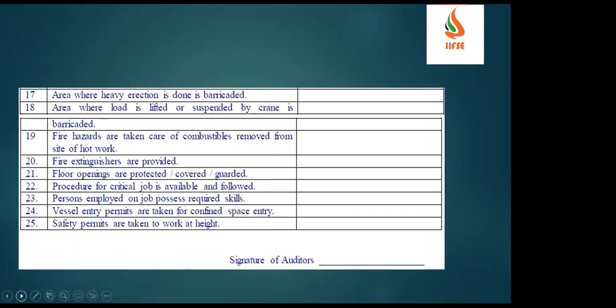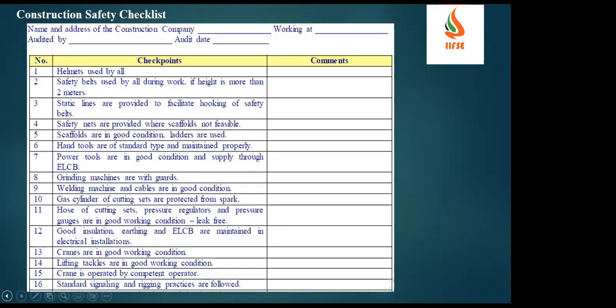Inspection, sir. Third party inspection. The competent person must inspect, and also they have to get third party verification for all the cranes, whatever crane it is, even safety belts, compressors, all lifting tools and tackles. All the things must be third party verified.